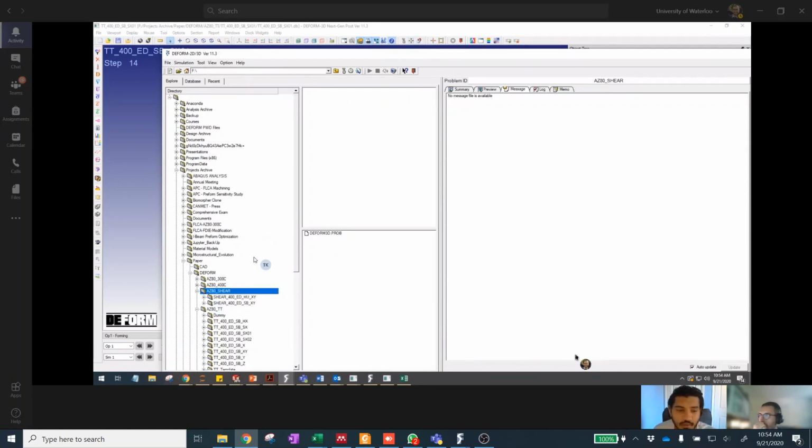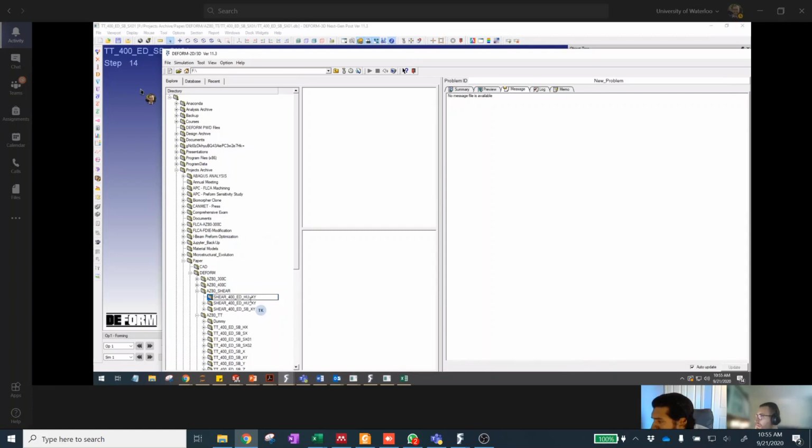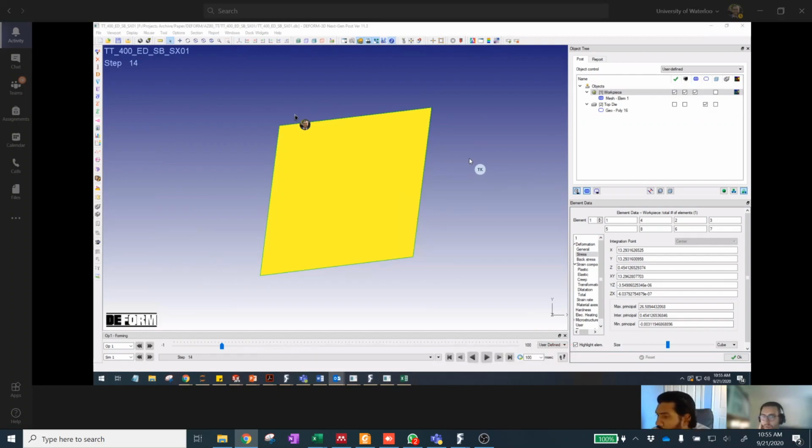So yeah, that was the thing. I just want to verify I'm looking at the right information to make this bridge, to see if I'm doing it correctly. Bezod's diagram there that has the boundary conditions imposed says his intention is to generate pure shear. What we're doing here, I mean, it is pure shear what you're getting, but it's not the same. His boundary conditions are kind of incorrect. I would say node 3 and 4 should not have a Y constraint on it. But he's imposing a Y constraint and then he's adding a load in that direction, which doesn't make sense to me. But anyways, continue with what you were saying.